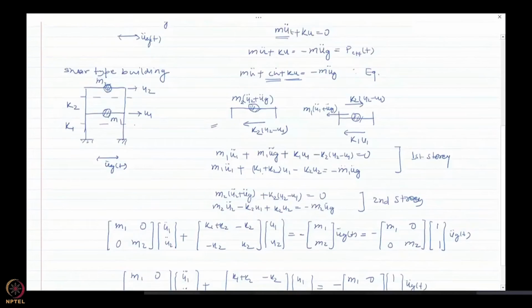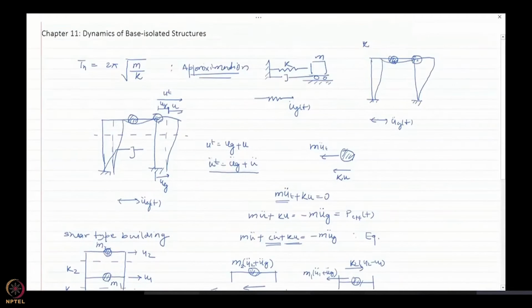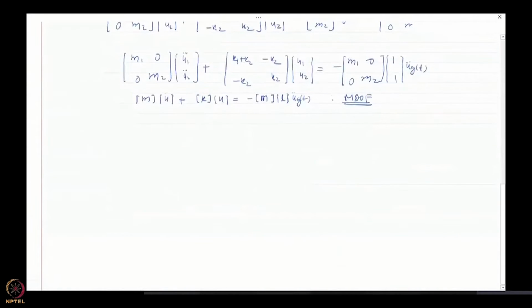Now, for a single degree of freedom system, we did not have any concept of contribution factor, because there was only one mode. But as you know, a multi-degree of freedom system is represented by different modes, and the overall response is the sum of the contribution of response due to each mode. That becomes important because let us say your structure has multiple modes. Multiple modes also means multiple time periods or frequencies,